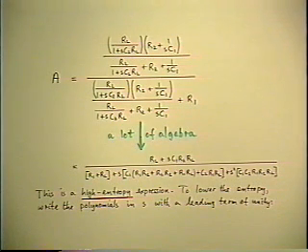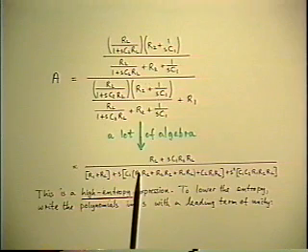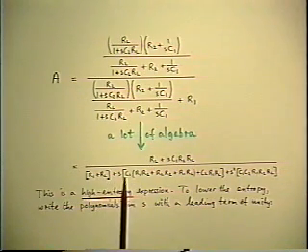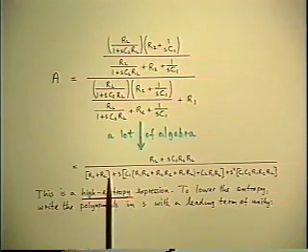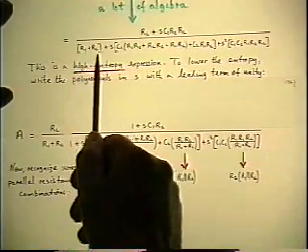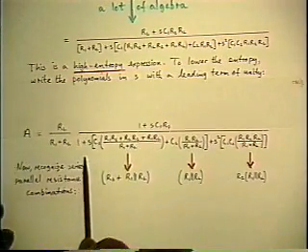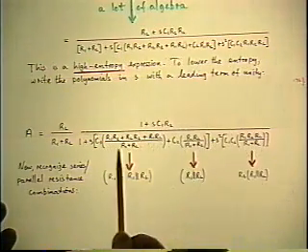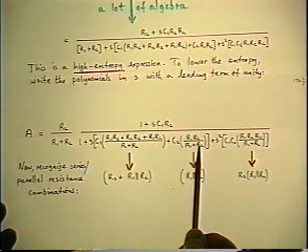although some of them may take the next step, which is to make each of the polynomials in S have a leading term of 1. And the way you get that, of course, is you pull out R1 plus RL from the denominator, which means you have to divide it into the second and the third coefficients.